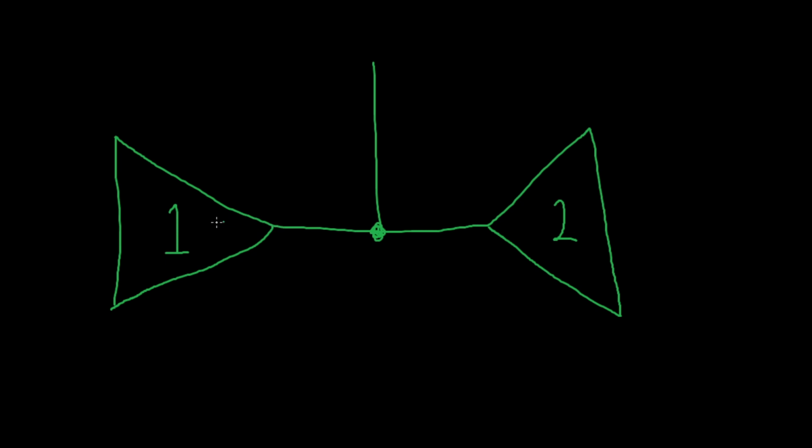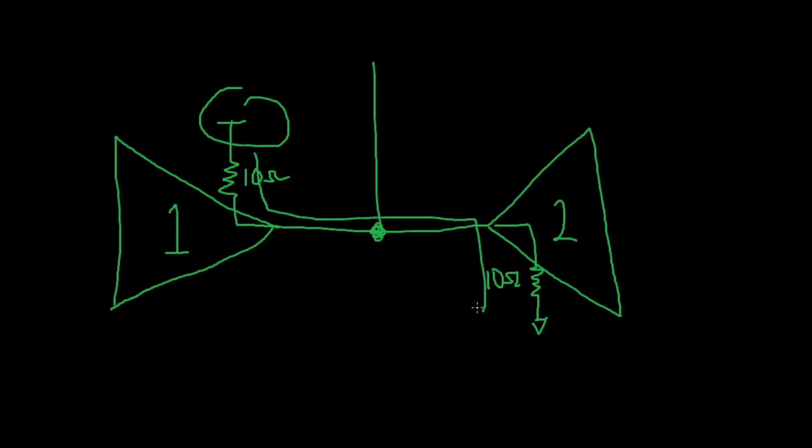So we can imagine this: if this device is trying to drive the line high and its MOSFET has a resistance of 10 ohms, and this device is attempting to drive the line low and its resistance is also 10 ohms, then that means we've essentially connected our supply directly to our ground with 20 ohms. That comes out to 250 milliamps of current, and most likely will immediately damage both of these devices and cause this bus to fail. This is something we call bus contention, and it's something you always want to avoid with logic.